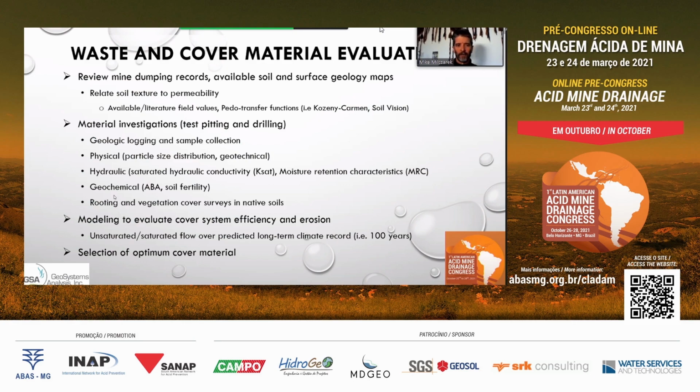Another thing that we like to do that's quite important is to look at rooting and vegetation in the native soils. So what do the native vegetation, how big of a rooting depth do they need? Is it 1 meter? Is that adequate, or is it deeper? The only way you can really do this is just to go and dig some test pits in native material and take a look and do rooting surveys. And that can also guide you as to what is an appropriate cover system depth that will support